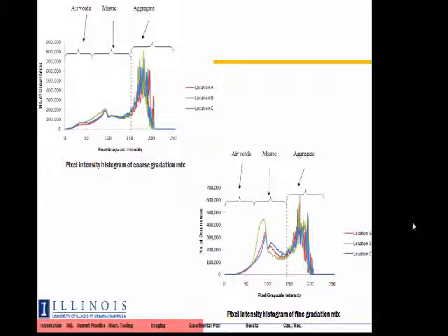What does that mean? We can define regions within that. Toward the low end, or the darker end of the grayscale, is considered air voids. Not all air voids are going to show up as purely black pixels because they're of varying depth and depending on the device used to capture it. So there is a range that is considered air voids. We see a small peak in the middle of this distribution, which comes from our smaller aggregate that have a tendency to be suspended in the asphalt binder. So it begins to contribute to that mastic phase that people are referring to.